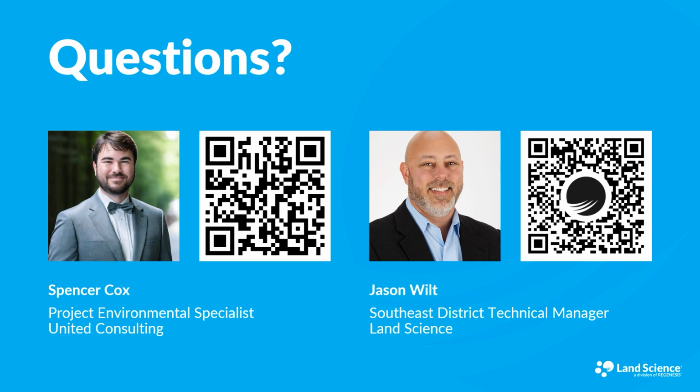So here's another question, and this one is for Spencer. And Spencer, it's regarding costs. Can you speak to the cost differential between passive and active systems, and how about the potential for those hidden costs? Sure. So, a passive system, if you think about its installation, you're putting down the vapor barrier, you're running the vertical stacks to the roof, and then you'll either be putting a passive, what we call a whirlybird, or some type of J-hook with a screen on them. And then typically you're not doing anything to those systems.